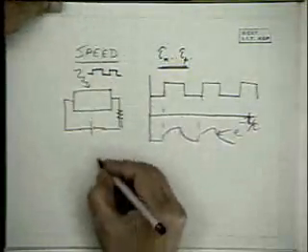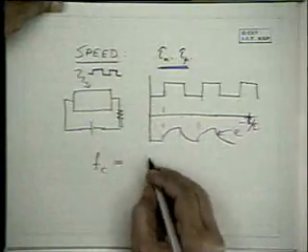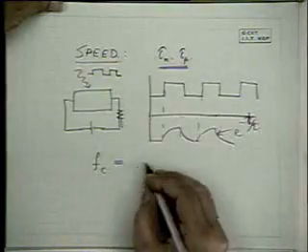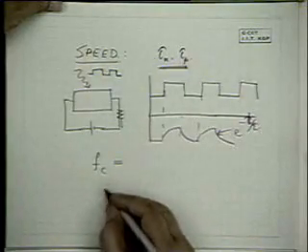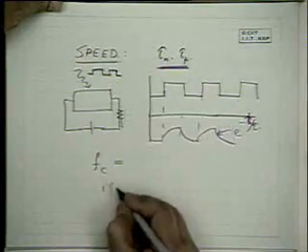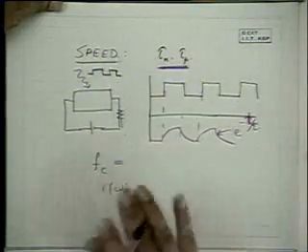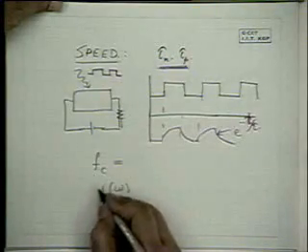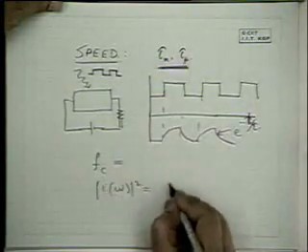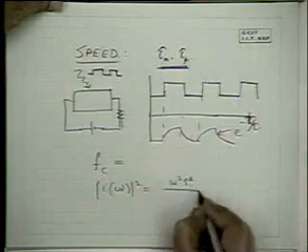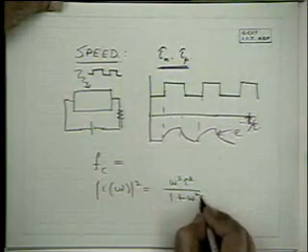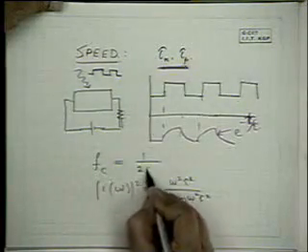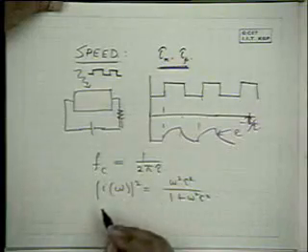The cutoff frequency can be shown from an analysis of the AC response, which I'm not going into. Suppose you have a modulated current at an angular frequency omega, then I omega squared will be given by omega squared tau squared over 1 plus omega squared tau squared, and from this you see that the cutoff frequency is nothing but 1 by 2 pi tau.